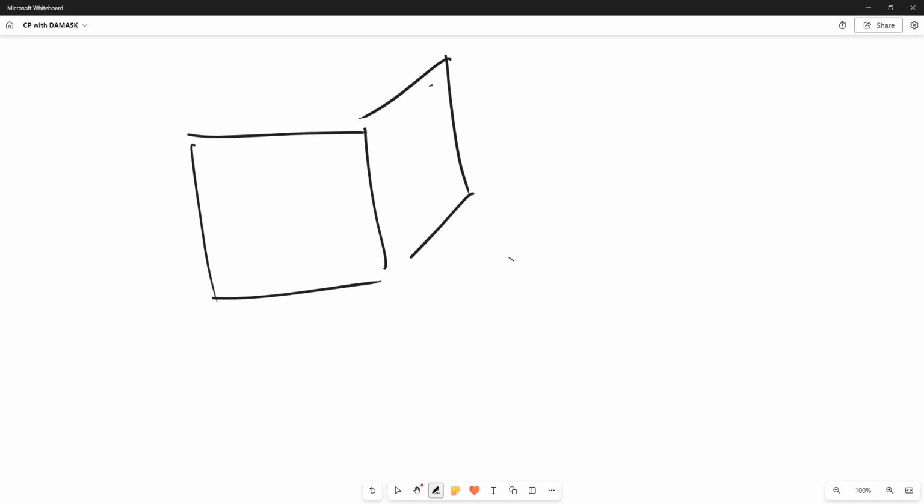In general, in metals we have a crystal structure. In most of the metals it is cubic, so face-centered cubic or body-centered cubic. And if I draw that here, it looks something like this, right? For example, if it is face-centered cubic crystal structure, then we will have atoms on all corners and on all faces, and then there will be some planes that are more densely packed, right?